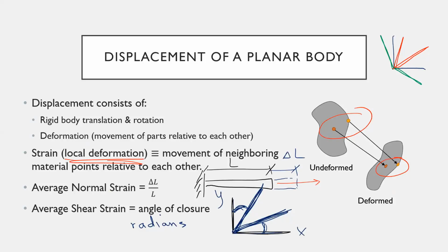And in particular, this definition of shear strain being the closure angle has to do with the two lines that you drew being your X and Y coordinate axes. Because if you think of, for example, a rectangle, and that rectangle, say, deforms, you have an angle of closure right here, but this top left actually has an angle of opening, right?